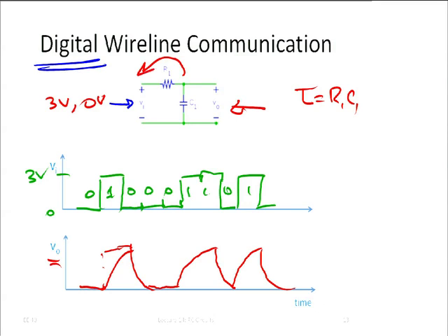Actually, the amount of information over Ethernet is less. It's one gigabit per second, and they split it up into 4 wire pairs. If you look at an Ethernet cable, there are 4 pairs of wires. They are smart: with 10 megabit Ethernet they used just 1 pair, but now with 1 gigabit Ethernet they use all 4 pairs, so each pair handles only 250 megabits per second.